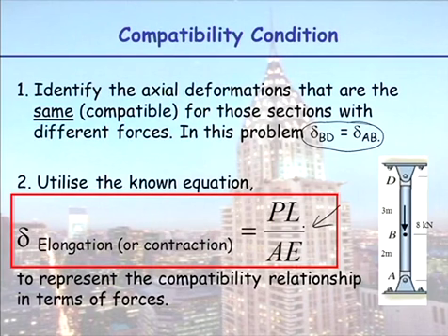So that's how we tackle these axially loaded problems. So in what we just dealt with, beam bending, we equated two deflections, and we had the beam bending formulas we utilised. Now we'll always do it in terms of PL on AE. And that last problem I just did, that was also in terms of one of the stretching forces, one of the movements was a stretching in terms of PL on AE.